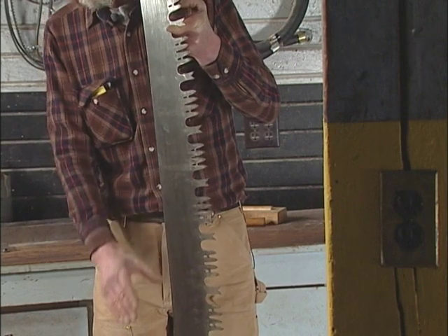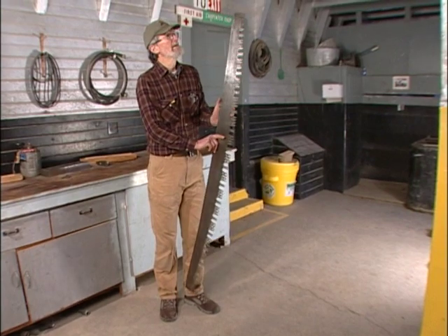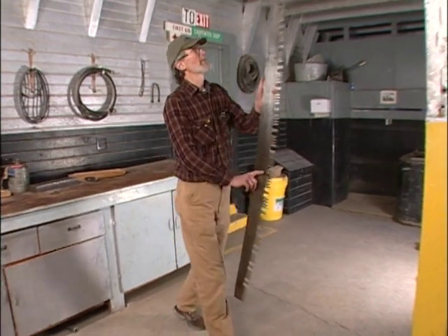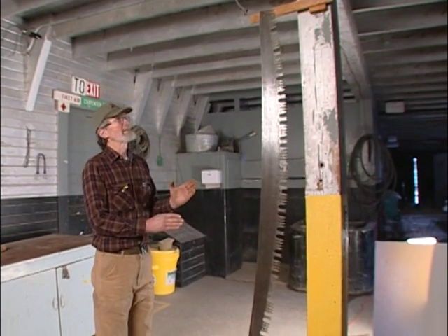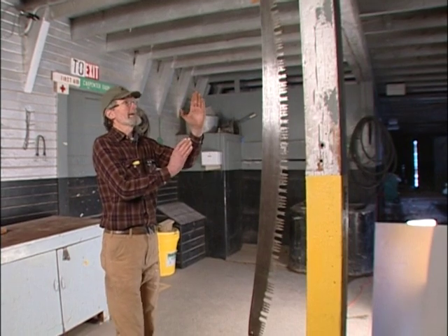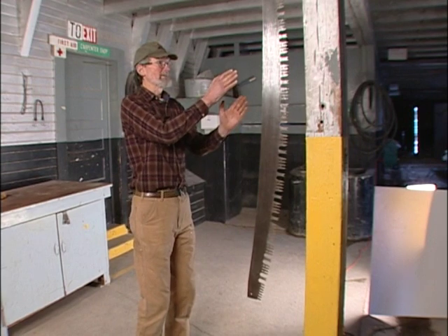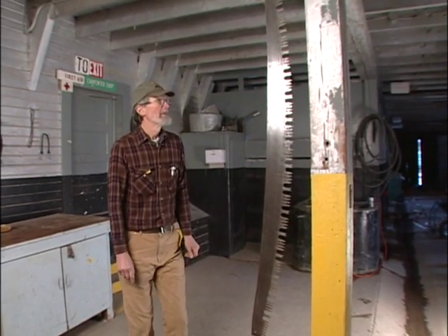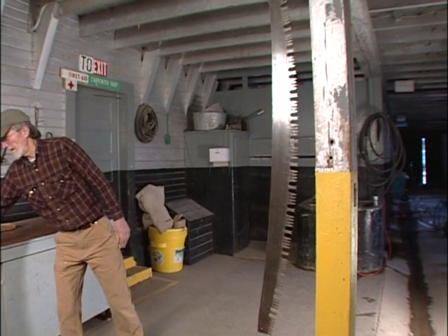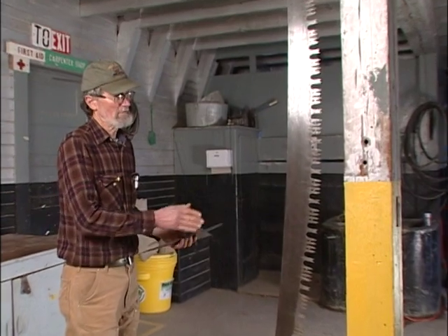Okay, once I've done a pre-look at it like this, then I'll hang it up vertically on some convenient place. And what I end up using is just a nail. And one of the important things about the support is that it let the saw hang freely, so it doesn't have any sideways torque on it, which in itself will put a little bit of a bow in the saw. Okay, once I've got the saw hung, then I need to go over it with the straight edges and determine more precisely where the bumps and the curves are.